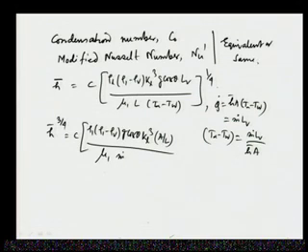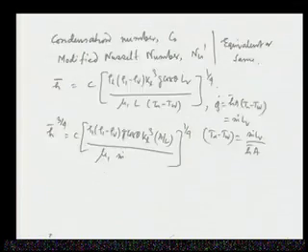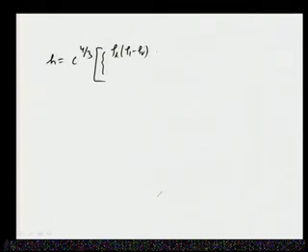So, doing some rearrangement to this, you will get this expression. Now, if you further do some rearrangements, we will get h as C to the power 4/3 and then rho L into (rho L minus rho V) into g into k L cubed by mu square, this is one part.